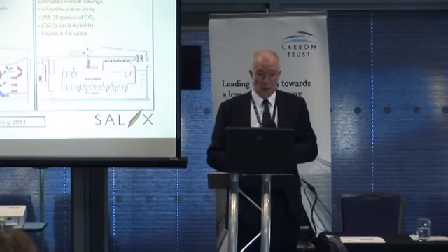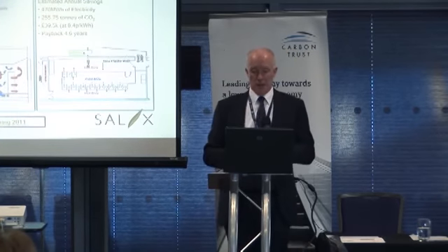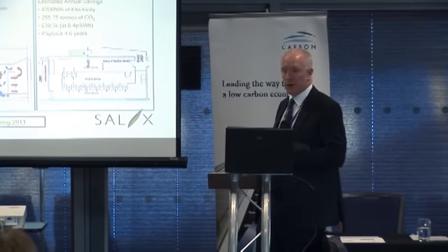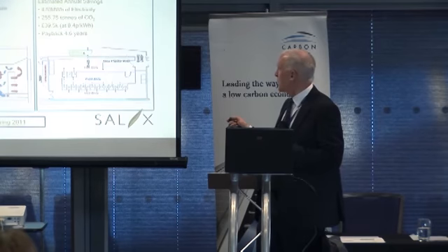And finally, perhaps more ambitious, Cambridge University here, doing some simple containment, putting up partitioning to create a cold aisle with a hot aisle on the outside. So simply doing what we spoke about a bit earlier, creating that. And then they've also put in evaporative cooling.